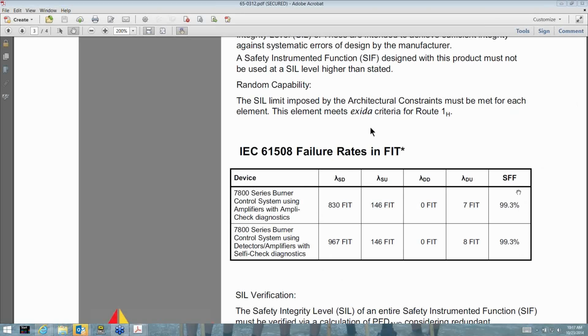So that would mean, you look at this device, it has a very strong pedigree. Going back to somebody coming in and saying my product is SIL rated, you really got to come back to this. It's not really SIL rated. It's a certification presented by a third party that gives you the numbers that tell you how this thing is going to respond, and that then gives you the SIL level that the product can operate at. So it's never really a rating, which I think is one of the important things to take away from all of this.